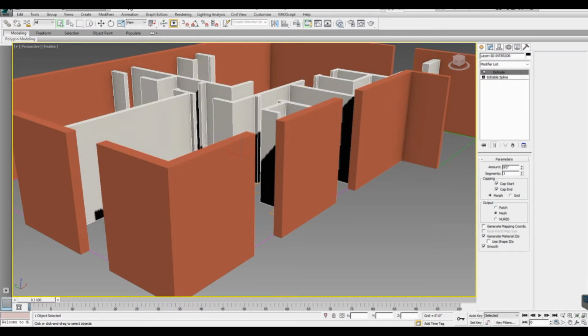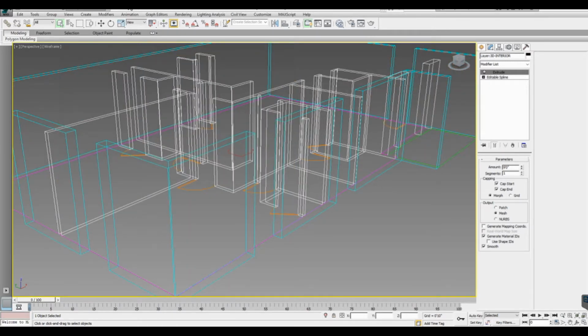We're going to take that off anyway, but if you hit the F4 key on your keyboard, you see how it shows all of the edges. You hit the F4 key again, and it takes the edges off. You hit it again, and it shows you all the edges. That's going to help your workflow a little better. You hit F3, and it'll take you into wireframe mode. We're going to actually be in wireframe mode a good bit while we're bridging our overheads